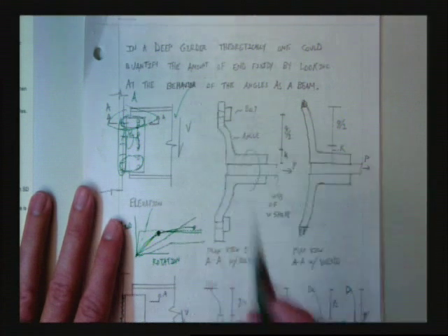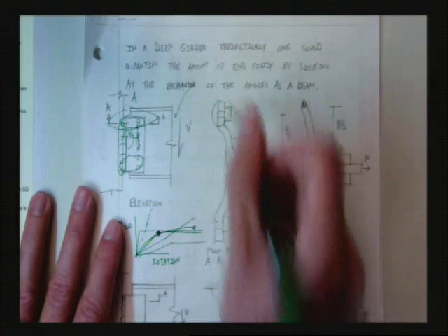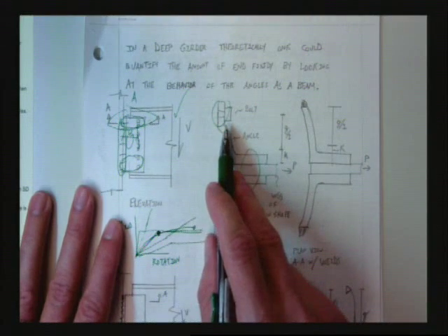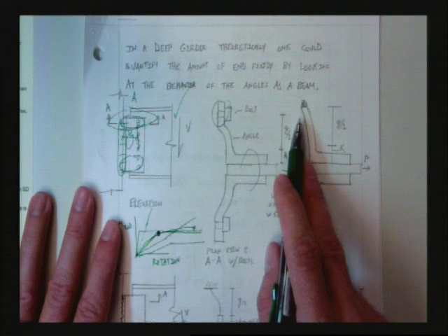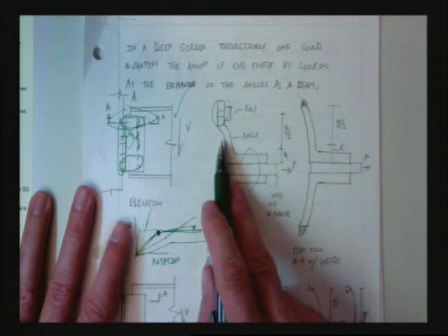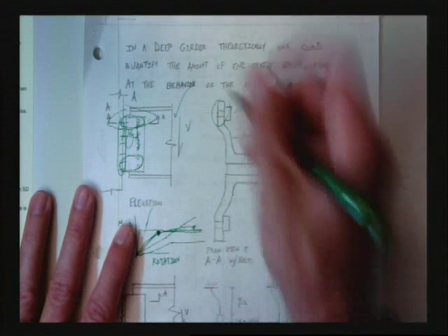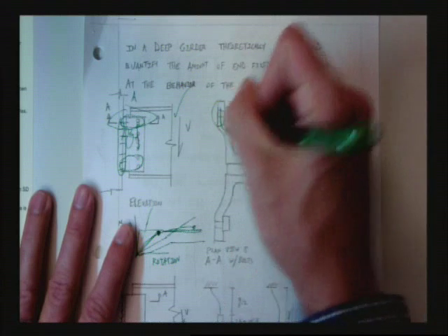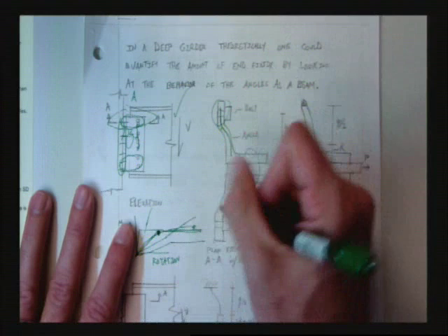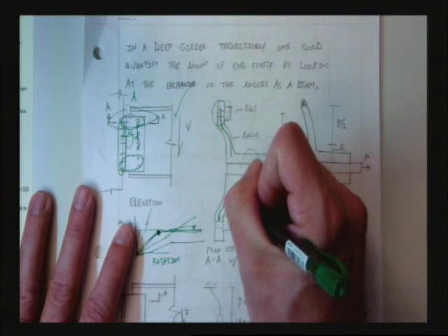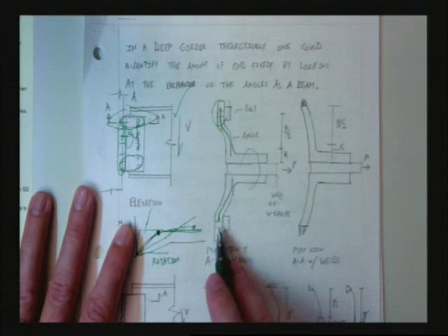If this is bolted, we're going to get some squeeze. We're going to get some localized restraint caused by the head of the bolt. And if it's welded, we're not. It's going to just pivot and rotate. Now, have we ever seen any kind of connection that we know how to deal with where it has almost zero amount of rotation, and then almost zero amount of rotation? We've seen that before? Yes, we have. It's a fixed connection, isn't it?